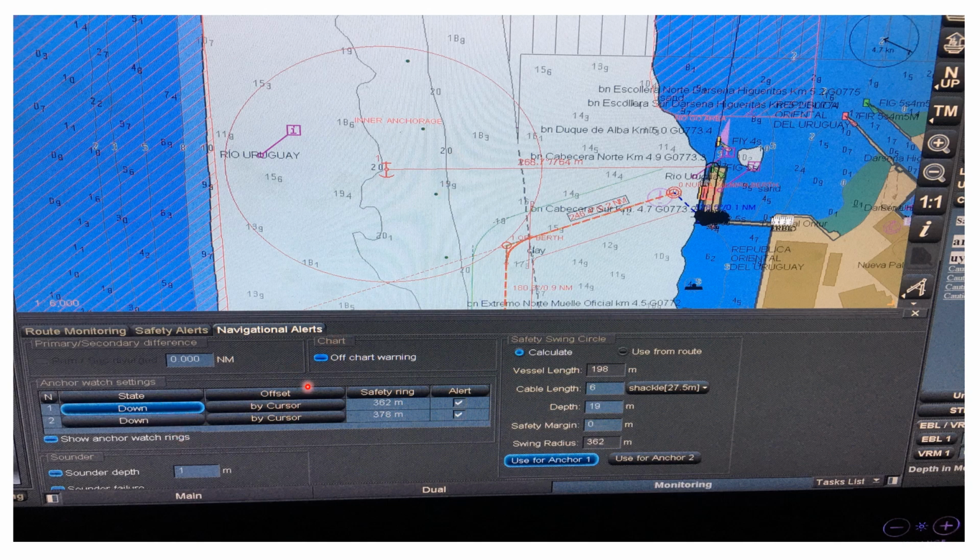This is another example. The vessel is still in the water. Then we want to go to the anchorage area. So let's say, okay, let's select the anchorage area. Let's see what will be the swinging circle when we drop anchor here. So you use by console and then you click here. The swinging circle will show, and the course line, the distance.